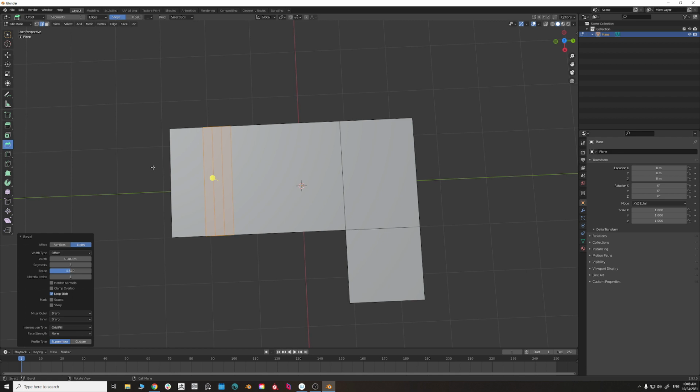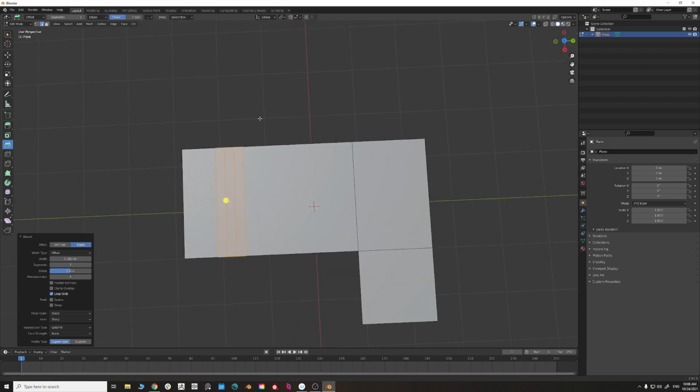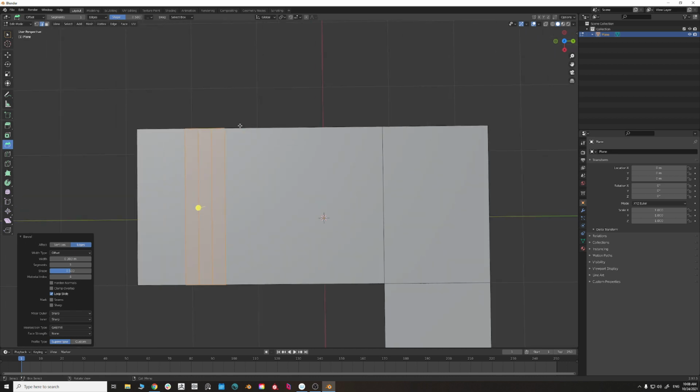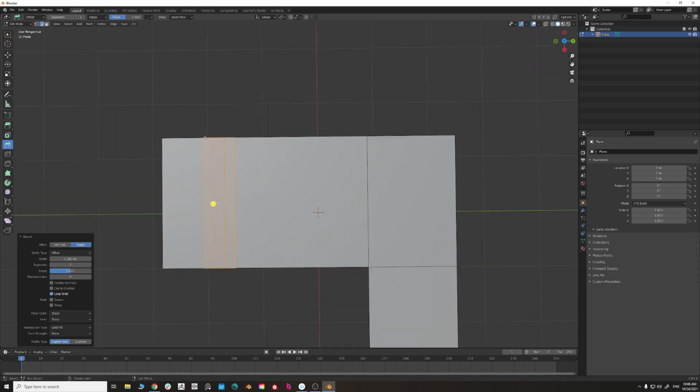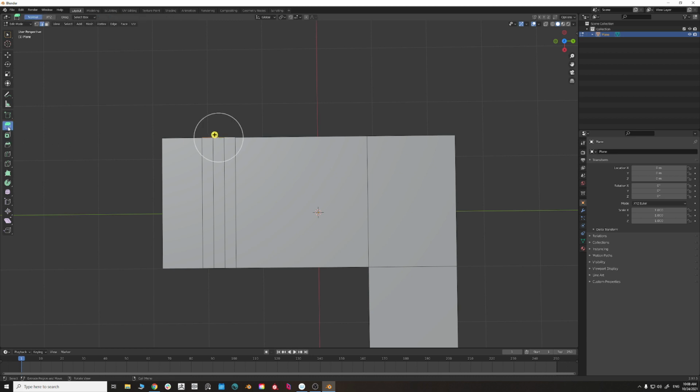And what I'm going to do, because I want it to pop out from the silhouette of the house, really like to sort of pop off, I'm going to select these 3 edges, and I'm going to use extrude region, and I'm going to restrict it across the x-axis by pressing X on the keyboard. And I want something maybe like this. We're going to have a chimney pop out of here eventually, so let's work around with this.